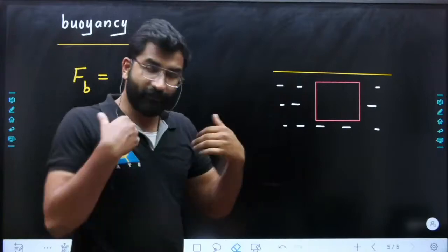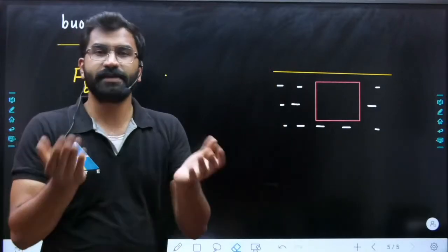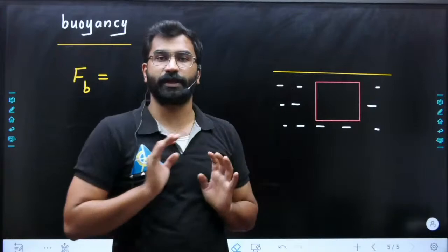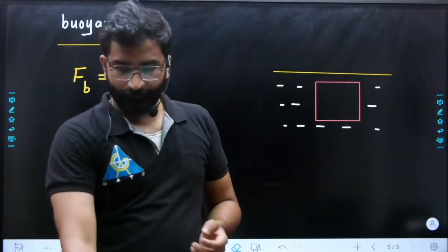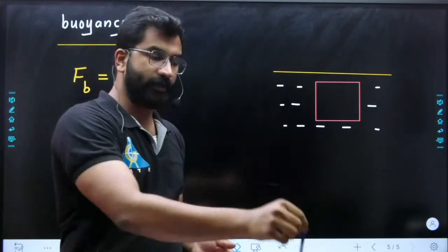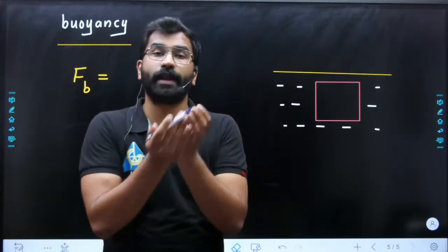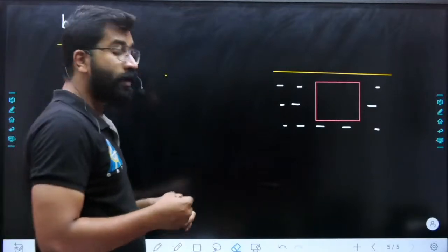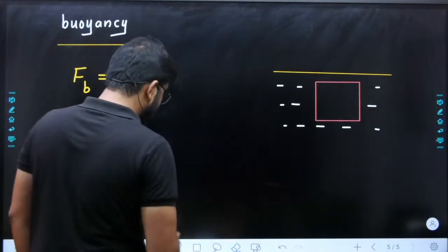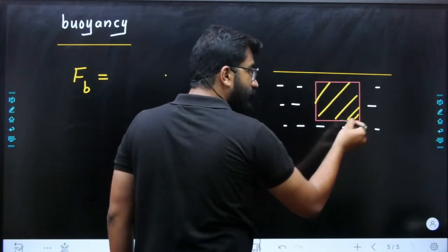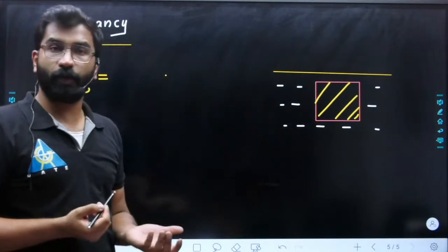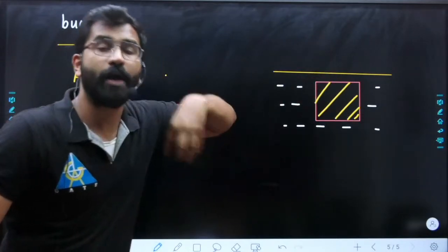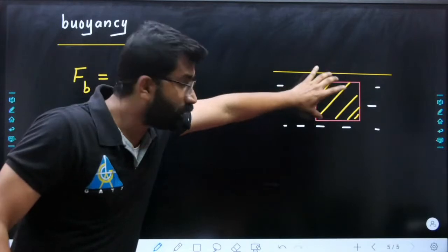That is, if I jump into water, buoyancy force on my body क्या होगा? It will be equal to जो भी पानी बाहर आता है, उसका weight हमें measure करना है. That is the concept, ठीक है? If I wanted to find the buoyancy on this pen, I am putting this in water. So you need to calculate the weight of water that has come out. Now here we want the complete volume of the body, because the body is completely inside the water, that much amount of water will come out, na? इतना complete body पानी के अंदर है, सो हमें volume किसका चाहिए? हमें volume चाहिए according to this much.